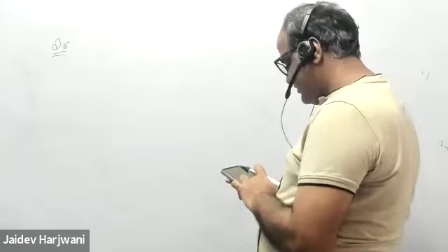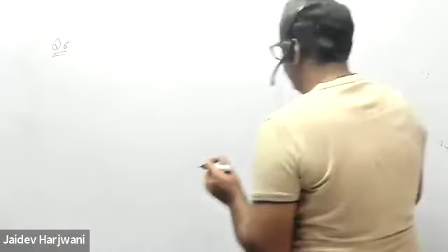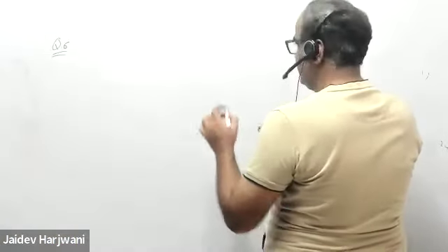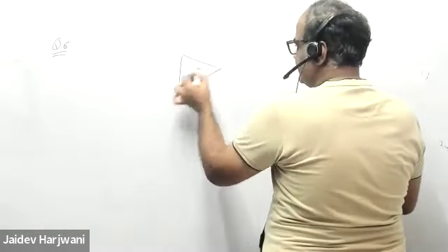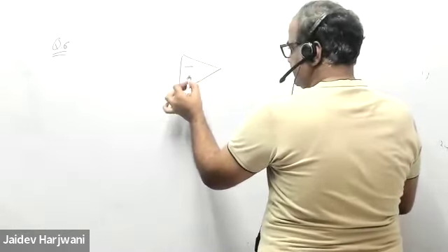In the given circuit with an ideal op-amp, for what value of R1 to R2 is the output of the amplifier V2 minus V1? Okay. So you are basically given a difference amplifier, with minus and plus inputs.